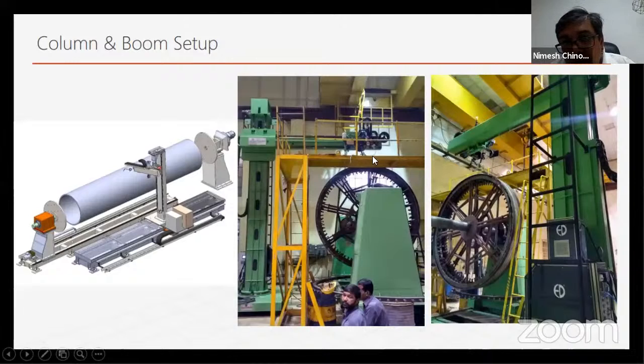The head here has AVC, weaving and cold wire feeder mounted onto a column boom setup. The headstock, tailstock rotates the job. We have the hot wire power source and the cold wire and the normal TIG power source, pulse TIG, which is controlled. The operator sits on the panel here on this floor, and he can do the welding from there. Again, the same 4 things give you the solution.